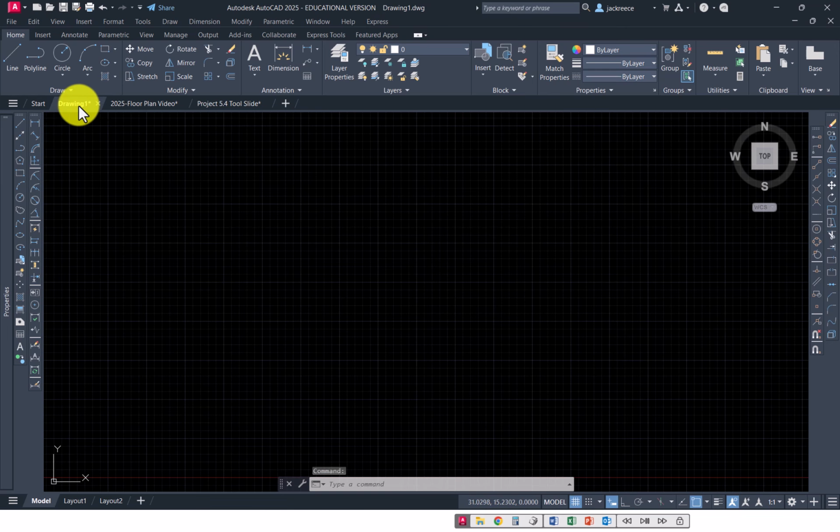These videos are just introducing you to what's covered in the first few pages of chapter 4. If you open up a new drawing, on the Home tab in the Layers panel, this is a quick way to deal with everything layers. The basic ACAD template just has one layer, called layer 0.